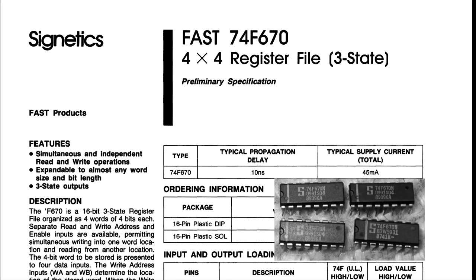This is the one I'll admit to. Got my hands on some 74F670 chips, okay? These are 4x4 register files. And so because I want efficient memory-to-memory movement, I thought, I can have 4 indirect registers, and that will let you do memory moves quite efficiently, hopefully.